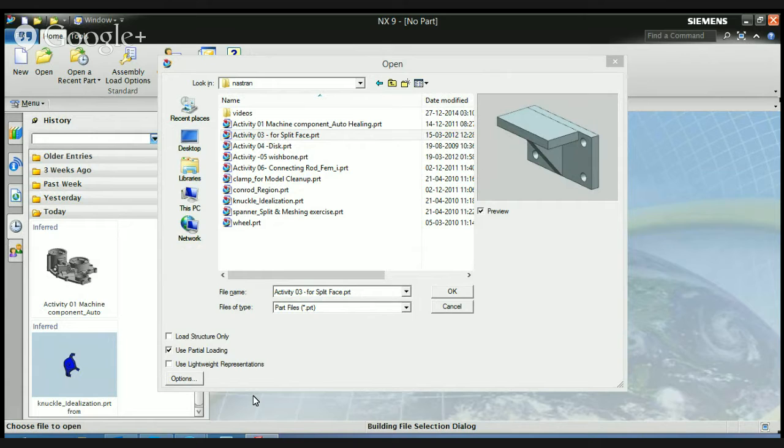So now the first section I'm taking you through is geometry abstraction. Geometry abstraction is nothing but creating our geometry for better quality of mesh. It will improve our quality of mesh, and it can make the boundary conditions and constraints much easier if you do geometry abstraction.